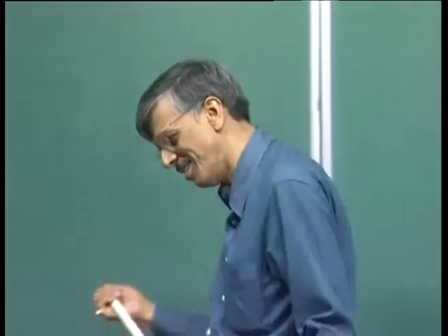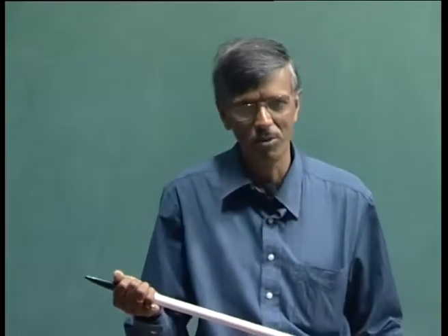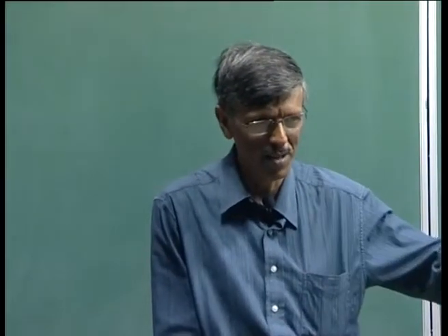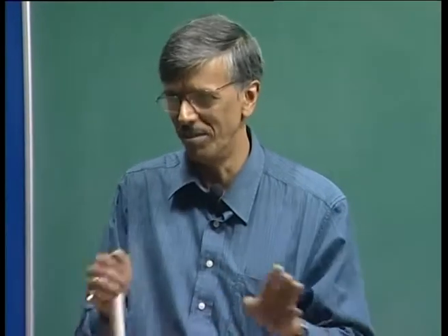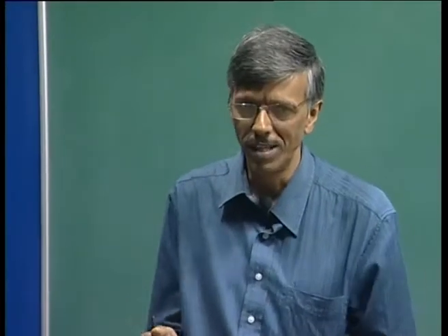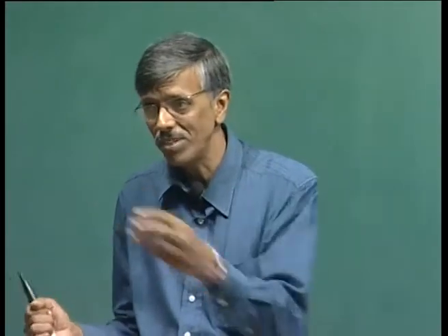So, what happened is that we figured this out in the mid-90s, and we were pretty happy that we could actually explain those modes in the left half plane, and we also found that for the Blasius boundary layer, these modes are not very harmful, they are docile. So, nothing greatly different happens, and that is why probably people were not alerted. If it was an unstable mode, somebody would have also seen it in some experiment.